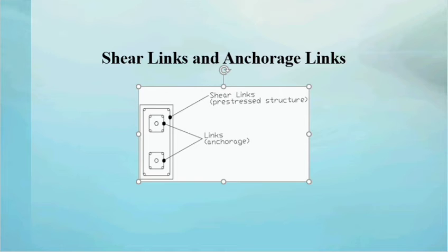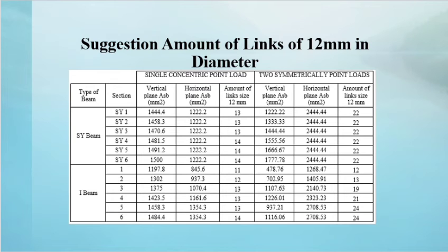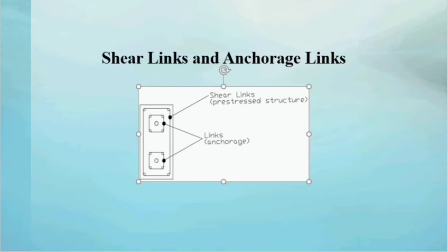After the required reinforcement is obtained using the formula stated in Eurocode 2, the engineer must provide a sufficient area of reinforcement so that the anchorage block does not split either horizontally or vertically. In the design stage, there is no specific number of bars that should be placed in the concrete structure. It depends on the preference of the assigned engineers based on the design standard verified by the local authority.